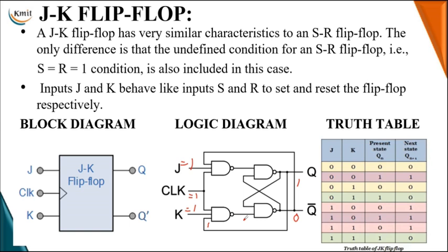If all 3 inputs are 1s, the output of the second NAND gate is 0. Next, the output of the first NAND gate, because of this 0 input which is a complemented output, is equal to 1. If the fourth NAND gate input is 0, then the output of this fourth NAND gate is now shifted to 1. Hence this 1 is transferred as the second input of the first NAND gate.